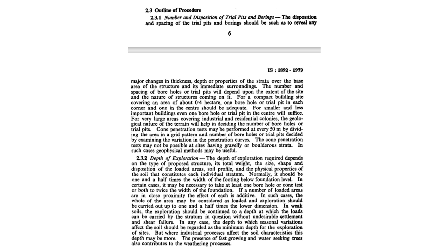Okay, so based on that trial pit only, you will be able to assess that initial vertical soil profile, and then you will get an idea. Okay, so this is the type of soil which exists. Obviously it doesn't go up to much higher depth, but it can form a base for your decision making. That is, this will help you to choose a better boring technique for your next level of subsurface exploration.